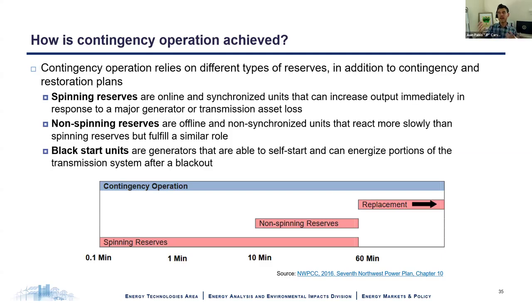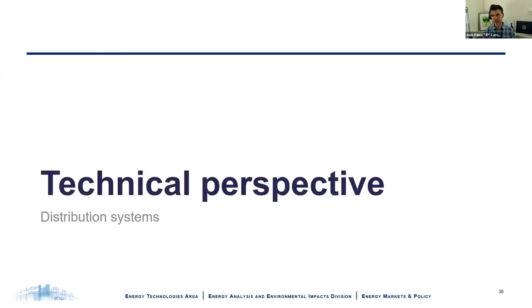These are all ways in which different units are operating, sometimes not at full capacity, and they give you a buffer for spinning reserve. And actually, wind and solar can provide spinning reserve by going down when requested and dropping some power, and that can be quite useful to provide services for contingency operation.